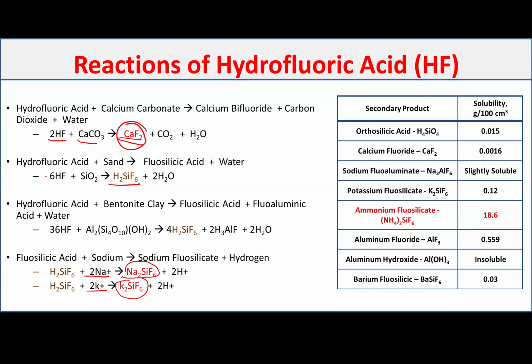And that's why, whenever we're talking about sandstone acidizing, we are combining both HCl and HF together. The reason that we're adding HCl to the HF is to keep the pH of the solution around 0, so less than 2. If it is less than 2, these two products will still be in solution and will not precipitate, at least near the wellbore area. Then you are actually pushing all this material deeper inside the formation.